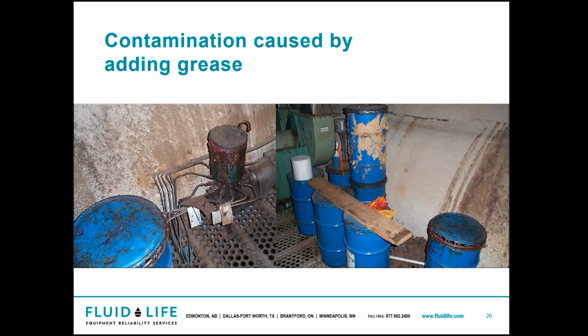Now, the other thing here is just poor housekeeping practices, and I'll give most guys the benefit of the doubt when I go on these audits, because they weren't properly trained on things, and I'm like, well, this is proper housekeeping. You can see the grease pouring down the side of it, and the other thing is it was overfilled. It's a little difficult to see from the photo, but it was overloaded with grease, and the cap is just loosely sitting on top of a pile of grease. And he explained to me that his logic was that it would close in on itself.